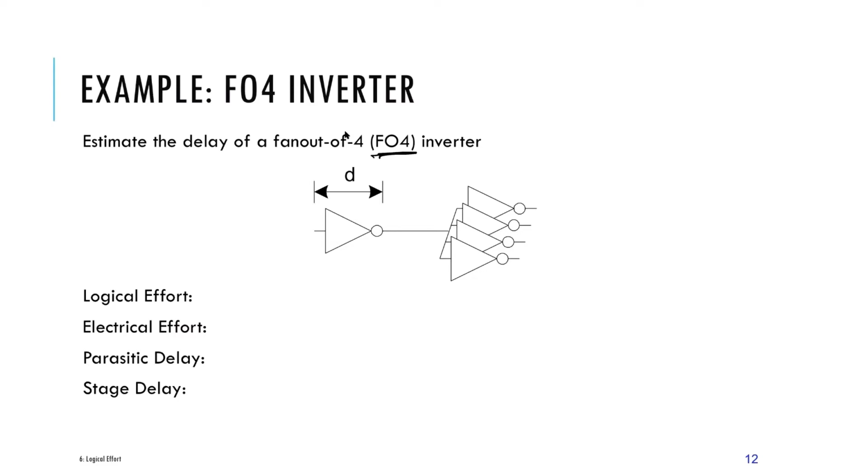Okay, guys, let's try to do it together now. So the logical effort is G. If you remember, we've got an inverter, so I happen to remember from our table, or you can look it up, G is 1. The electrical effort is H, so that's the fan out. In this case, we're driving 4 other inverters like ourselves. So H is 4.